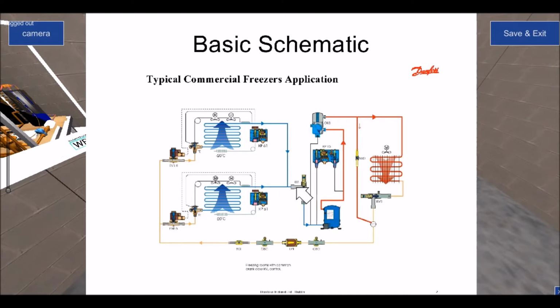Therefore, the back pressure, in other words, the pressure going back to the compressor, goes down or starts to decrease. And basically when it gets to zero, we have what's known as a low side pressure switch. So it's the pressure switch that makes or breaks the electrical feed to the compressor. So in other words, again, there's a bellows and a spring pressure. So we would set this at maybe cut in at 2 bar, differential at 2 bar.